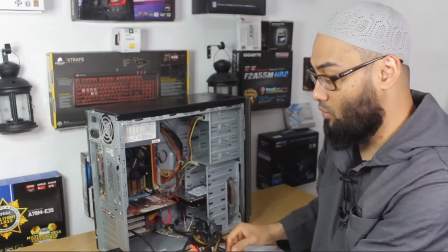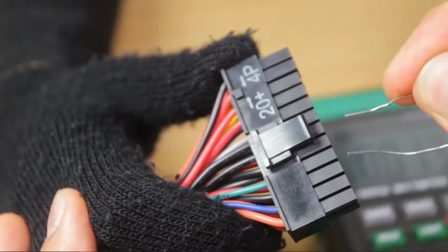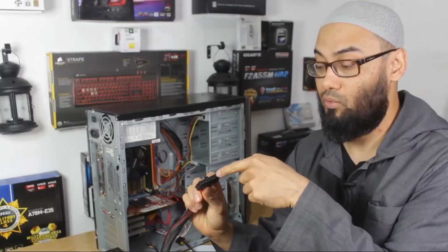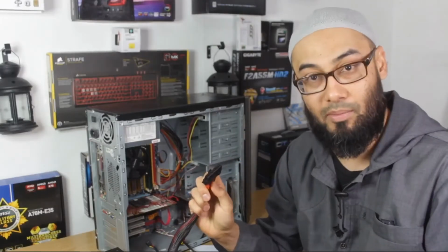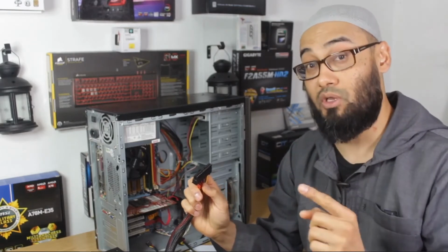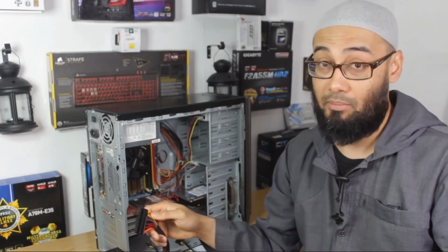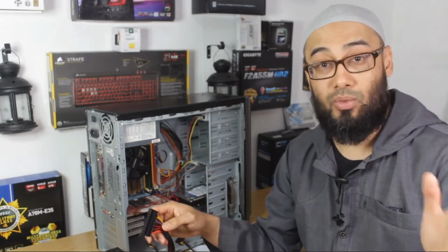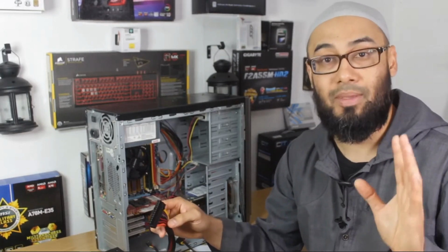And in which case, what we did was what's called the paperclip test. Essentially, we plug it into the mains. Before that, we bridge the green and the black cable to try and short it, and then we turn the power on. So we did find out that my power supply wasn't working because it wouldn't turn on, and we tested with a power supply which does work using the paperclip method.